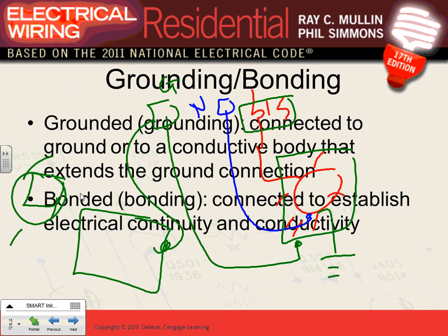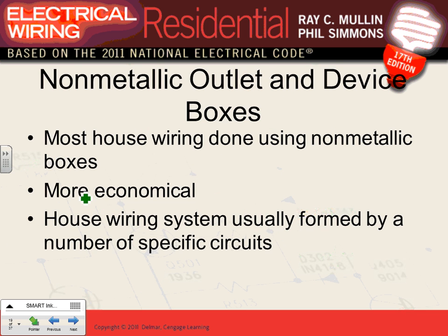So that's the equipment. We ground the equipment ground conductor to facilitate the operation of the overcurrent device. Bonding is to put everything at the same equipotential. We'll talk about this in detail as we go into the commercial and industrial. Just keep this in mind while we bond.